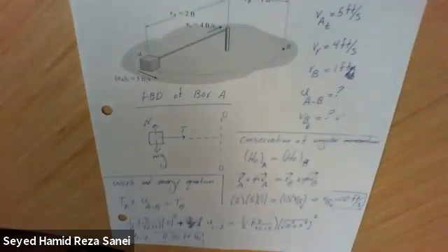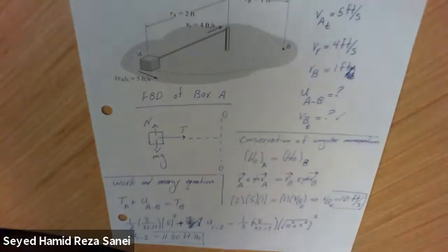If you look at the equation and the solution, there are a couple of important points that we need to pay attention to. When we read the problem, we need to know what method we are going to use. The best method to use here is angular momentum, because we have conservation of angular momentum. We don't have conservation of momentum.